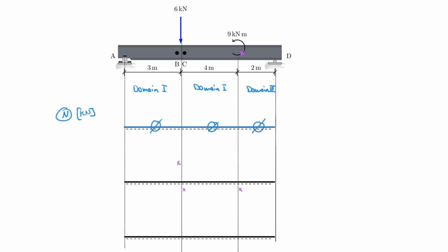Now, can I extrapolate my understanding from previous problems and from what I've learned as I set up the equations? Yes, I can. So what influences the shear force distribution from here to here is really only the support reaction. And remember, that was actually 5. So really how I should draw my diagram would be up with 5, because that's my RAY. So this is RAY.